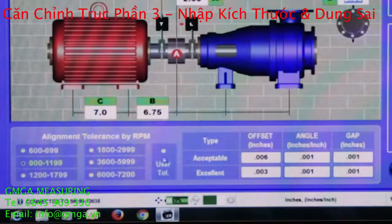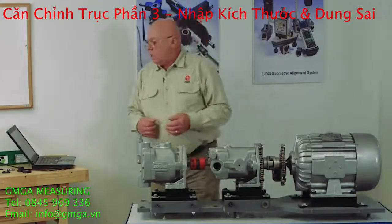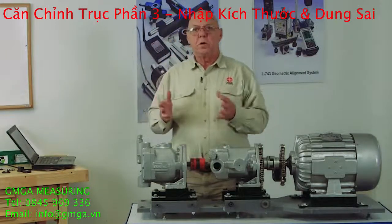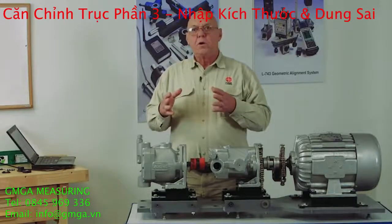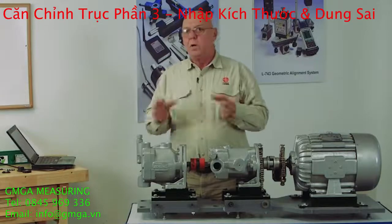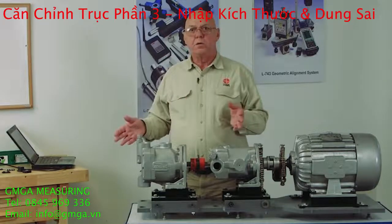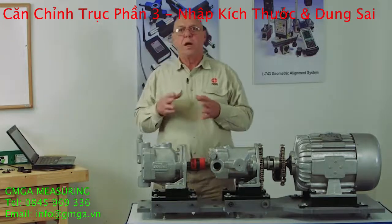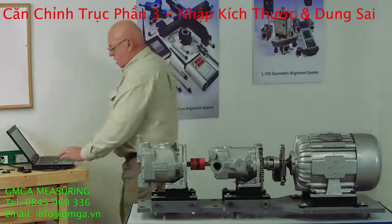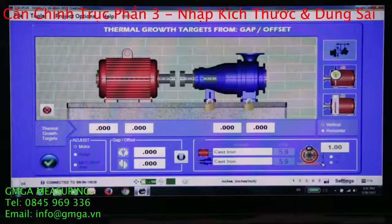But if you have different tolerances, you don't like these tolerances, you can click this user tolerance and you can put your own tolerances in there. Now these tolerances, they're not going to change the alignment. What they're going to do is make the arrows go away once you hit that tolerance. The numbers aren't going to change. The numbers aren't going to go to zero. The arrows will go away. The shim values may go away. These are the tolerances I'm going to give it for this motor.